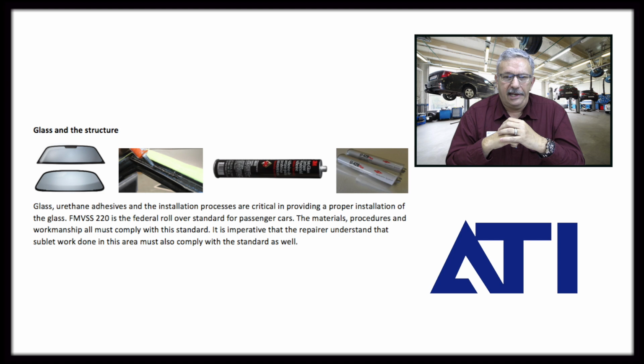The area where that adhesive is going to be placed once the vehicle is painted needs to be taped off so that you have bare metal there, so that when the urethane primer is put on, it is going on bare metal. That is a requirement of most of the adhesive manufacturers. You cannot put the urethane over fresh paint.